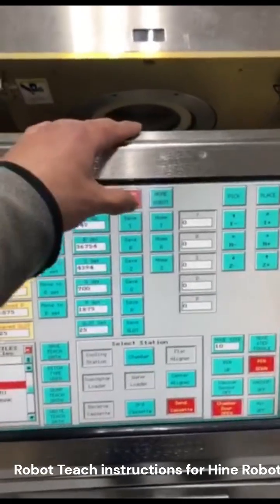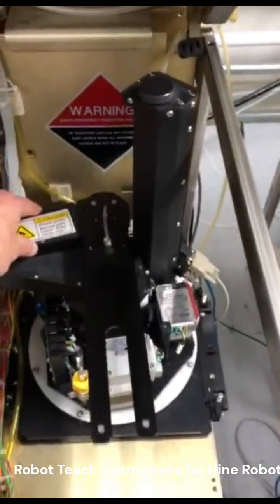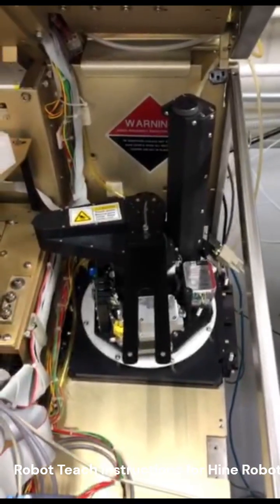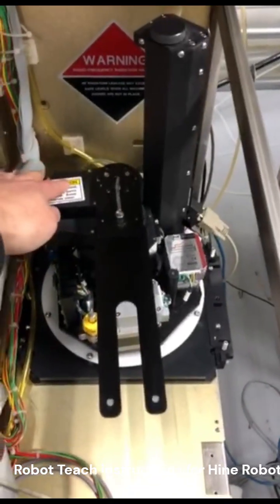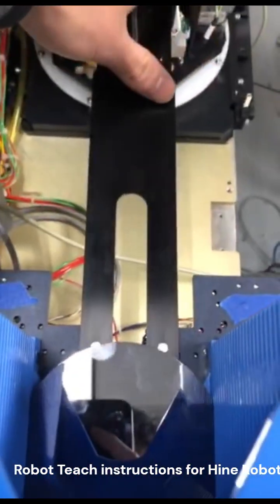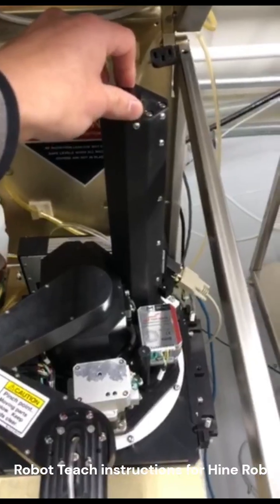First, stop the robot. Now you should be able to move the robot by hand manually. Bring it to the position that you want it to be taught. So in this case, under the first wafer in the cassette. Use the knob up here to adjust the Z value.